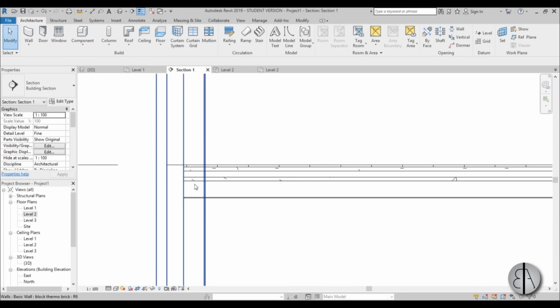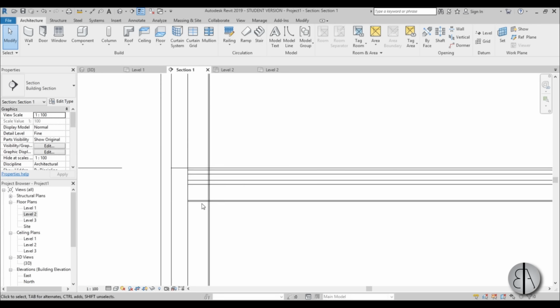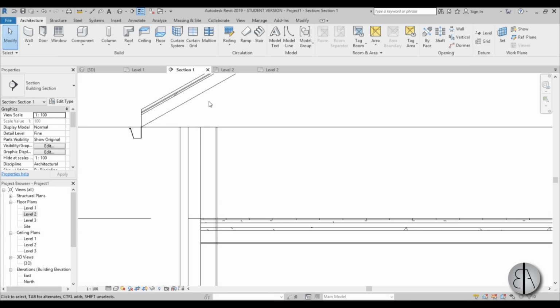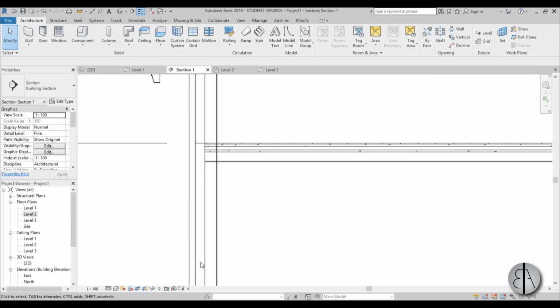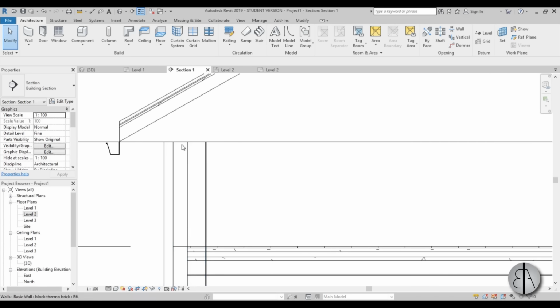So this is what we're looking for, because this floor is actually standing on this structural part, and then we're building a second wall, or second structural part of the wall, up here, and then the insulation and all the finishing layers are added on later on. Okay, one more thing here, this wall can't really end like this.